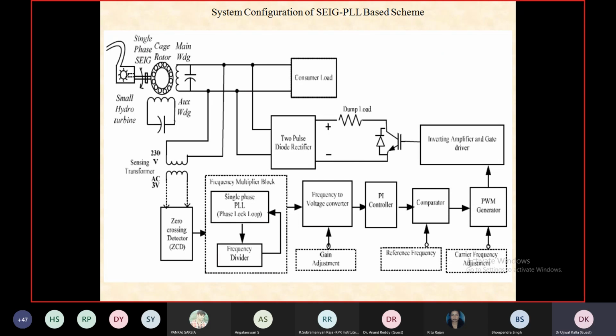Then I developed a multiplier. I multiplied that error in frequency by 10. Then I found that when I multiplied that signal by 10, the starting point of that waveform was different. Because of the phase difference in different output waveforms, again the output of the F to V converter was not okay. So then I developed an analog PLL. Using that analog PLL, I developed a frequency multiplier.